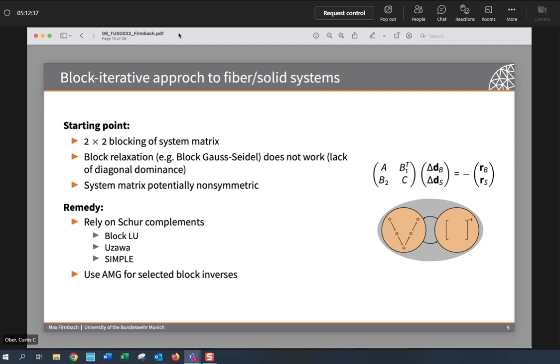What we actually do is call MueLu once to create our fine level, basically. And we restrict it to that fine level, and then with another XML file that we include into this one-level restriction XML file, we call MueLu again from the inside to generate the single block approximation.